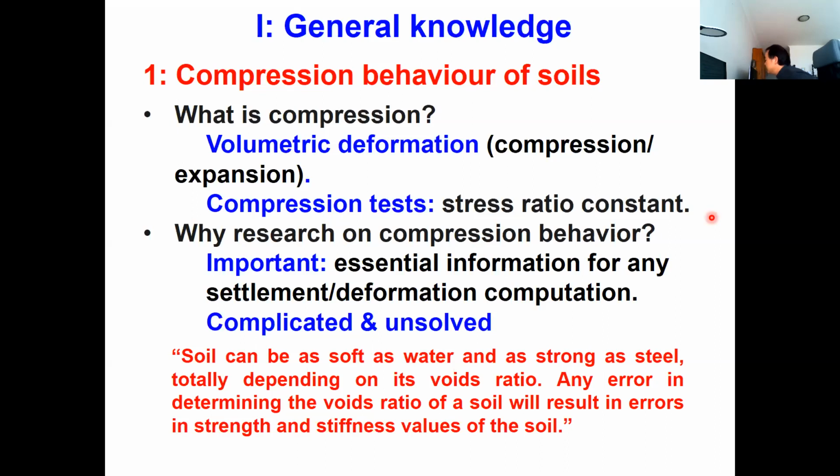That information is needed for settlement calculation of our structures, or even the deformation of our geotechnical structures. So if you want to do any deformation computation, you need to know the material parameters, and usually the material parameters are obtained from compression tests. So it's very important.